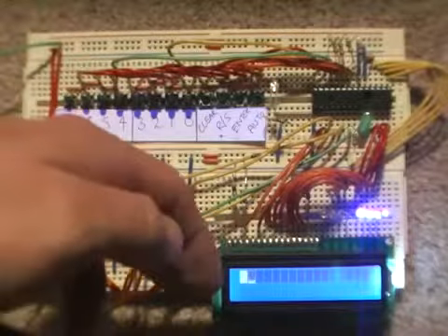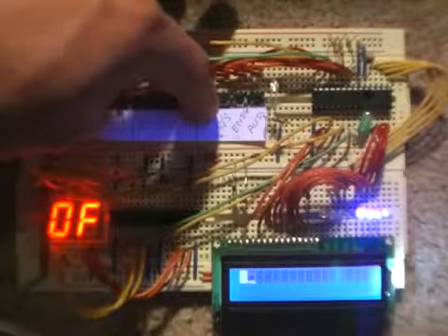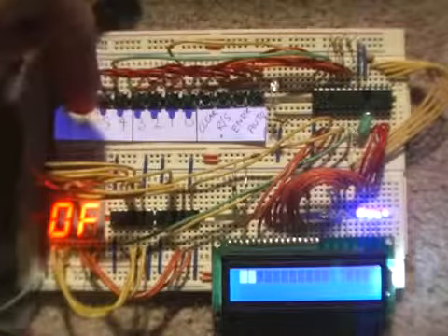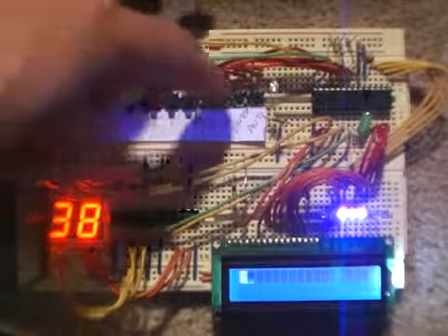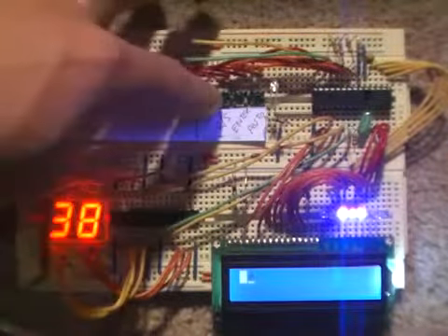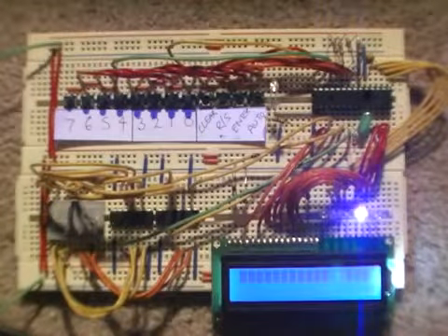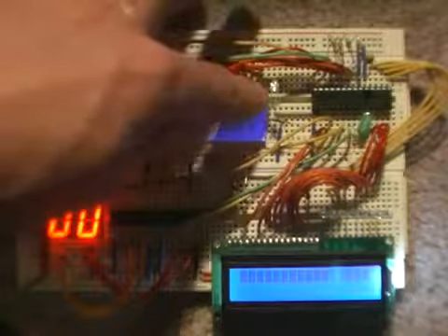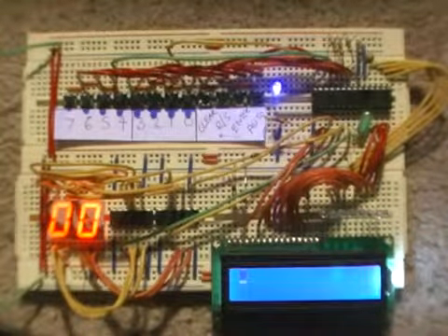I've got a bit of a glitch there. And to turn it into 2-line mode, I can clear that and press 00111, and that's changed to 2-line mode. All the auto switch does is do all that and set it into character mode, ready to type.